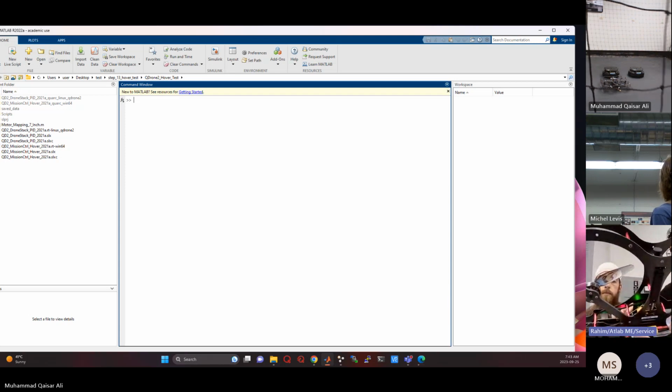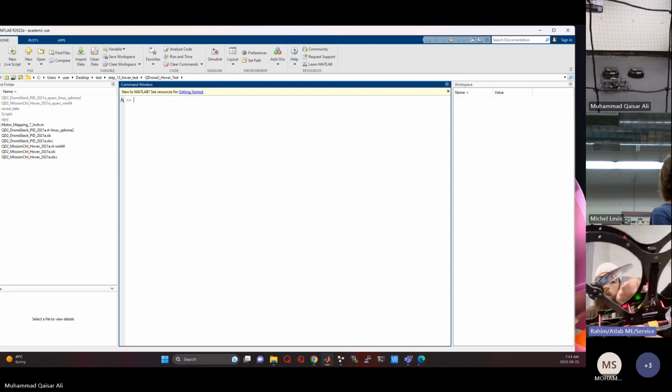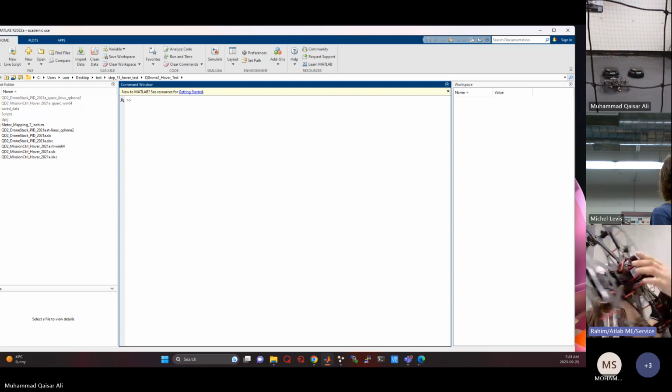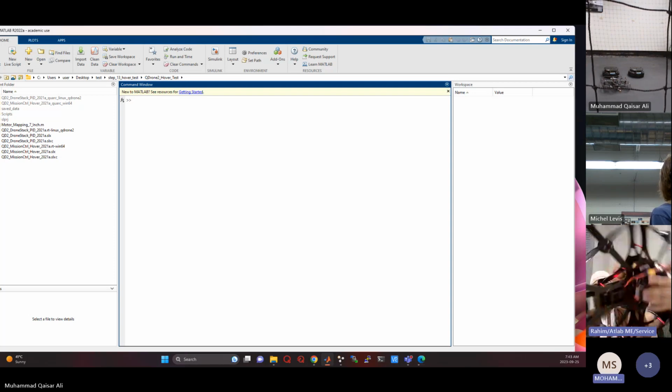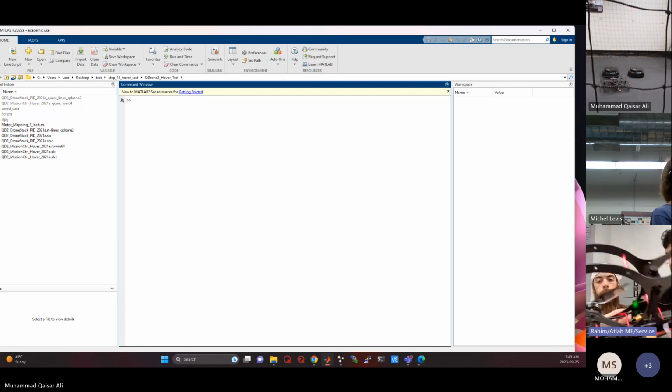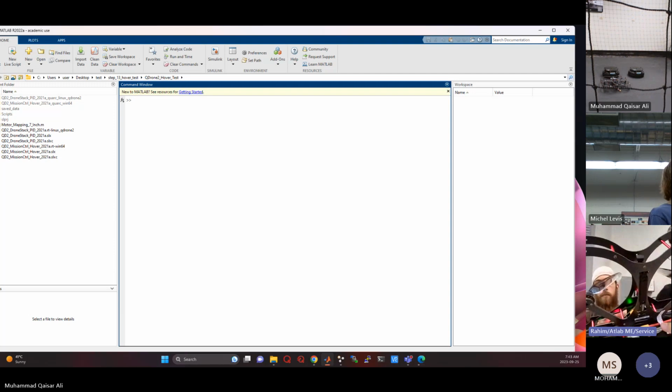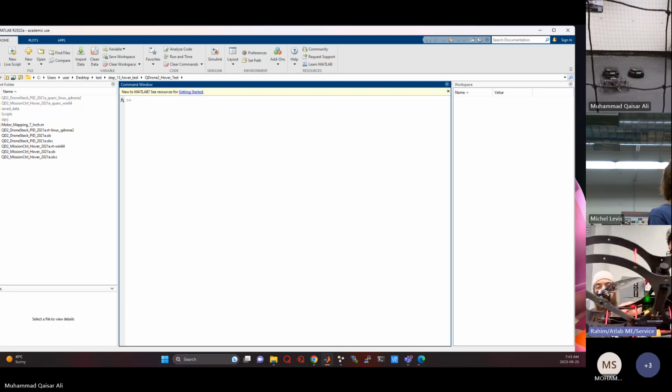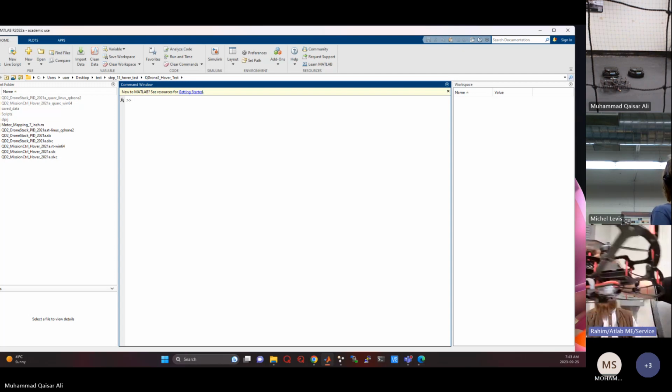Then how can we recharge it? You have to disconnect and pull the battery out, and charge the battery separately. You have spare batteries. So we have 16.5 volts now. Is it the nominal voltage? No, it's fully charged now. The maximum per cell is 4.2.